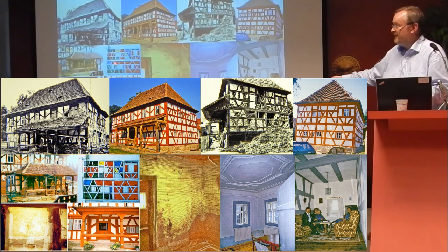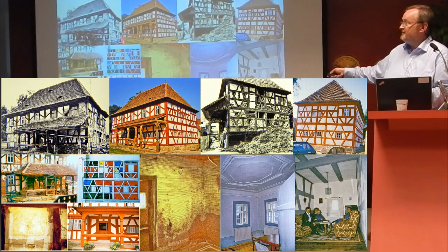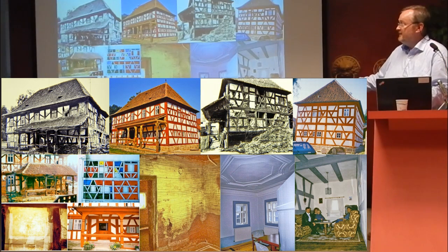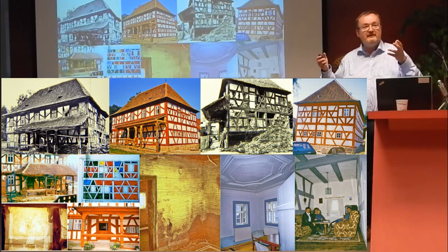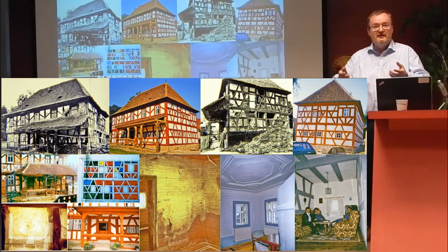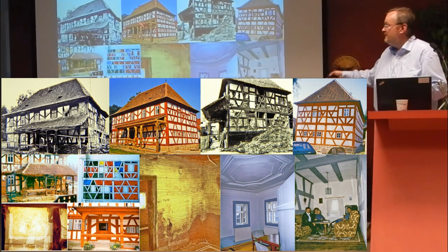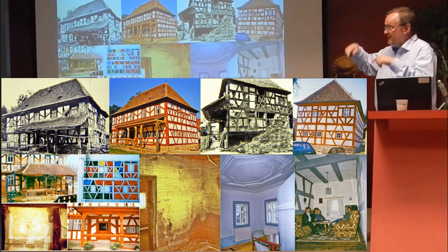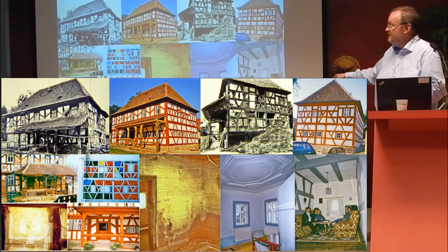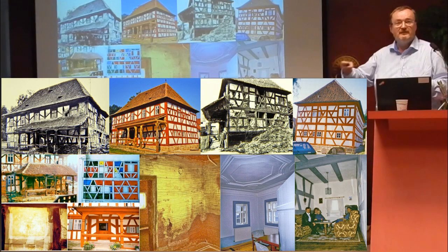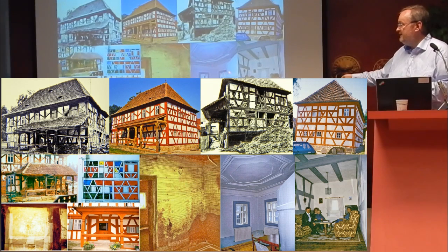So we have a catalog for every part of the building, and in the end, first we stabilized the whole facade, then we lifted the complete house 50 centimeters, repaired the beams at the socle, and then it comes down again. Then the inner surface we coat with a reed, then comes new rendering.